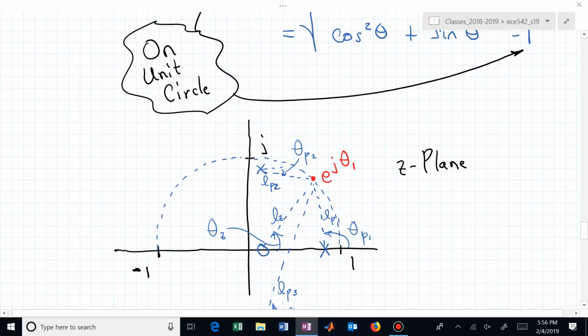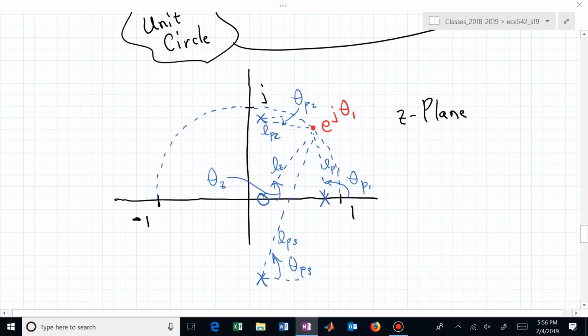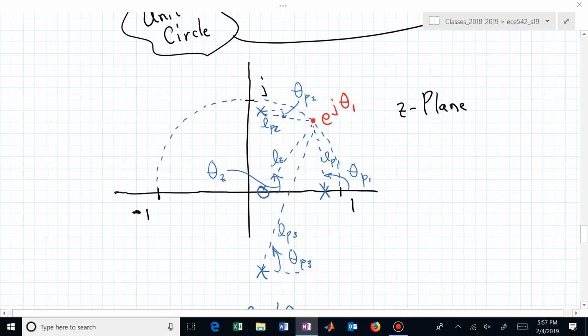Now suppose somebody gave you a transfer function, H of z, in pole-zero form, and they've translated that into x's and o's on the z-plane. That's what I've done here. How many poles are in that transfer function H of z as depicted in this diagram? It's a pretty busy diagram. Can you see how many x's there are? This is like a Where's Waldo, but it's a where are the poles. There's 3 poles, and how many finite zeros? 1. So this is now a 3-pole, 1-zero system.